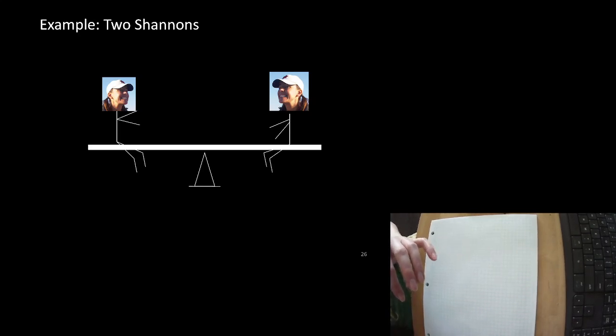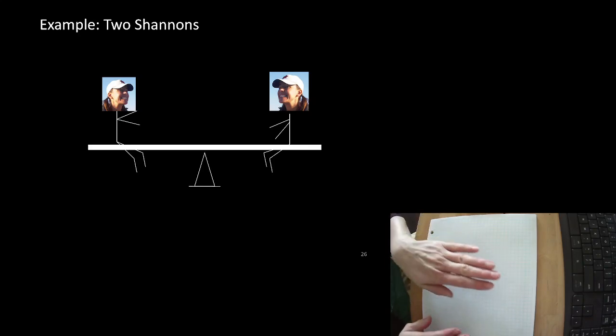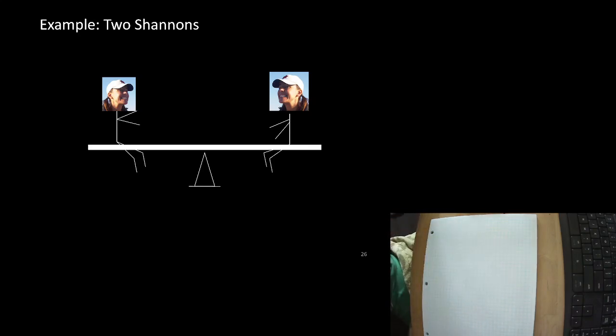Okay? So a teeter-totter, we know this teeter-totter is not sinking down into the center of the earth. That's not what it's doing. There is this pin holding it up. This is where I say you understand that a pin stops things from moving up and down and back and forth. But you know that this does not stop it from spinning about this point. Okay, so you understand a pin reaction.